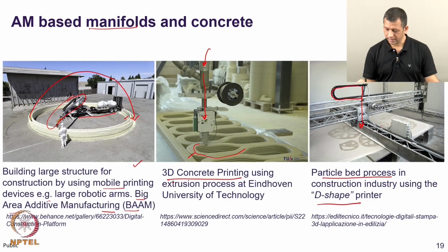There are two rails here. The lower rail spreads the particles and also levels it. The top rail runs over this bottom rail and is used for controlling how water can be sprinkled. The lighter part here is a powder bed which has all the ingredients like mentioned earlier. The darker part is the one where water has been sprinkled already.